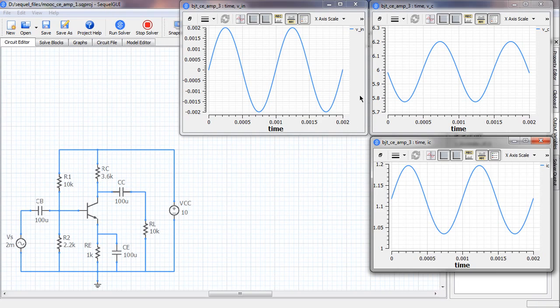So you can apply an input voltage of 2 millivolts amplitude and see whether your output voltage does indeed look like this. In the lab, you may not easily be able to apply an input voltage with amplitude 2 millivolts, and you may need to use a potential divider arrangement over here, but that's fairly straightforward, and hope you'll be able to do that.